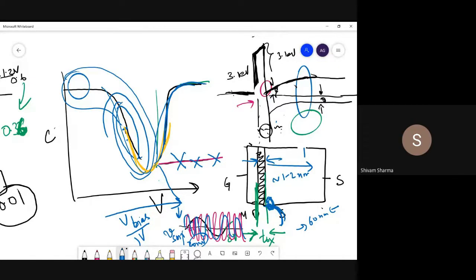So if you see the gap in dielectric thickness, it is 30 times, let us say. So no wonder you need 30 times more area when you implement a metal capacitor for the same value. So it is coming from the foundry side, basically, how it is manufactured.